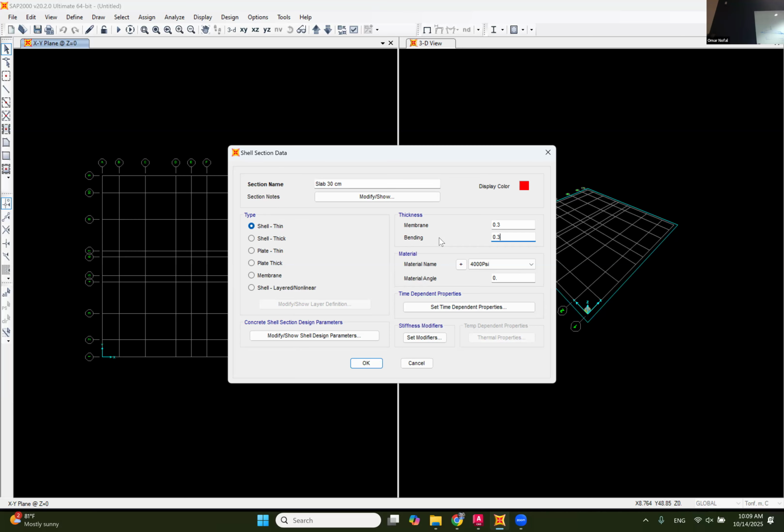You guys know that because the stiffness is much bigger in the moment of inertia, right? So that's what we do. But is this what happens? Is this wall only going to take load in this direction? No. Some loads are going to come in the other direction and make bending on the wall. So this wall is going to bend that way and that way, maybe when torsion happens, and it happens.